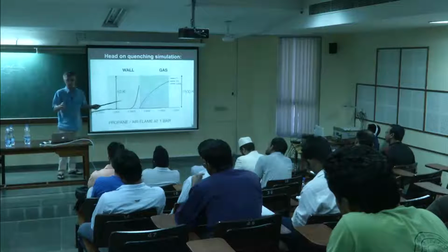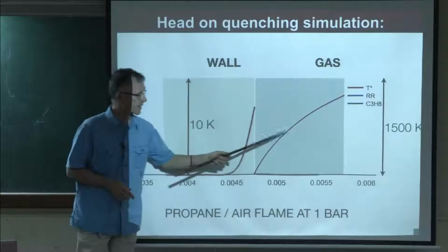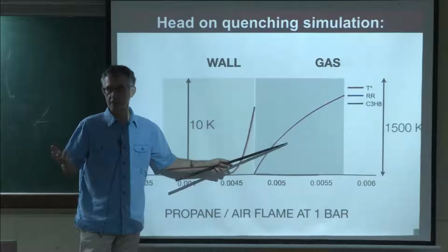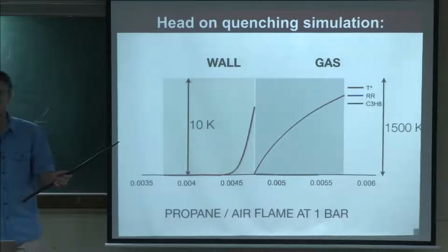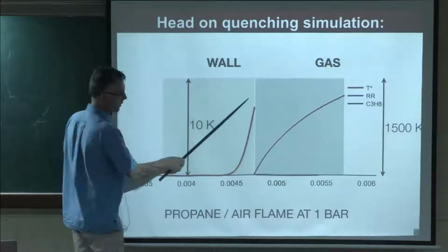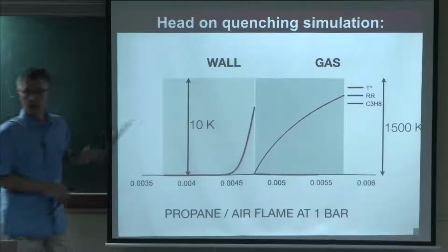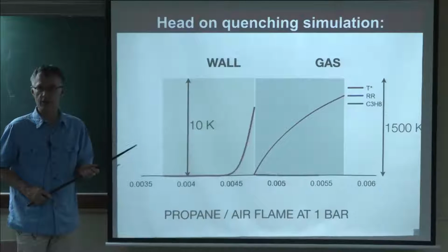Again, because it's something I will describe in a minute, the characteristic time of the flow here is 1 millisecond. The characteristic time of a wall of metal is a few minutes. So if you come back after half an hour, you will find a temperature like this. But for the first flame wall interaction, that's what's happening.